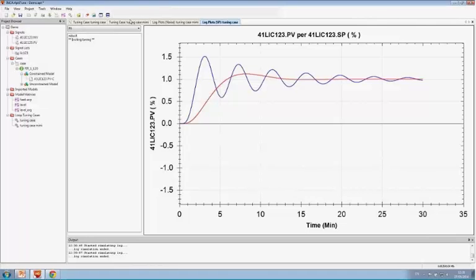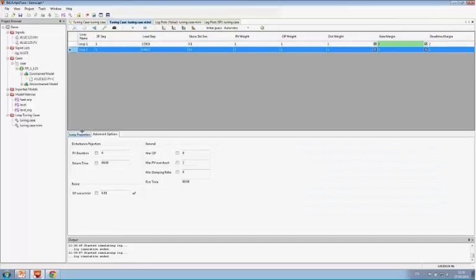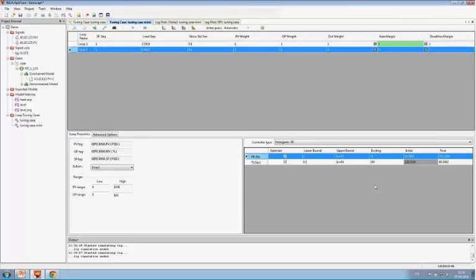So you can just type in the existing. Yes, you can, and this has two purposes, because if you type in the existing, you still know what the existing tuning was, and you can make comparisons as you go along. During your tuning project, you can log different controllers to see how they react and keep track of what's happening.